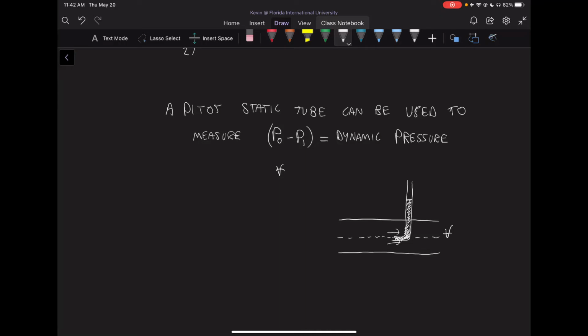But essentially what a pitot-static tube is used for, it's used on airplanes, it's used on many different applications. We can find the velocity of flow by converting the flow to 0 velocity and using the height of this column to figure out, okay, we have this much pressure in the system, so we can find the velocity of our flow. We decelerate the flow until we have essentially 0 velocity.